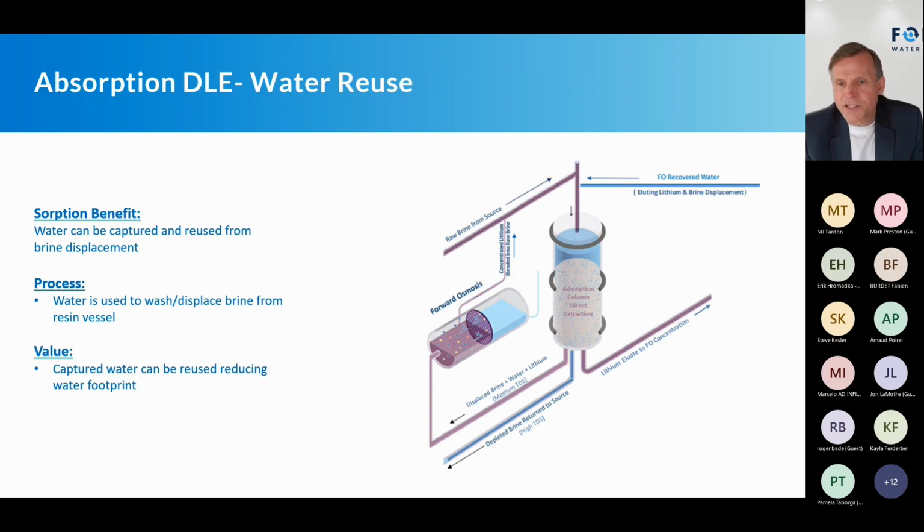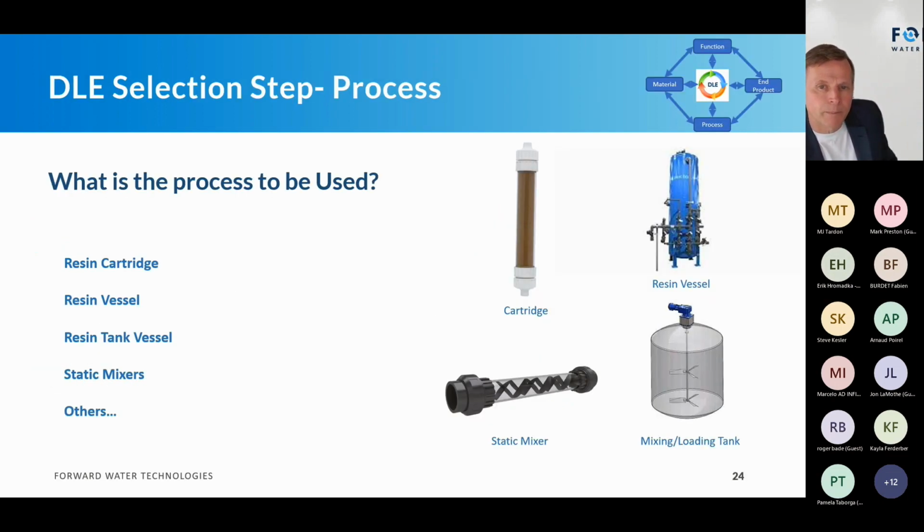During that process, as I'm putting water in and pumping it out, I've got a diluted brine solution, which is the opportunity: it's a lower TDS, so I can recover that water. So I'm just saying that on the absorption material process, during the displacement, you could recover that water. That's not the case in an ion exchange, for obvious reasons, since you're not using water for displacement. So it's something to take a look at, particularly in water stressed areas, that you can recover that water.